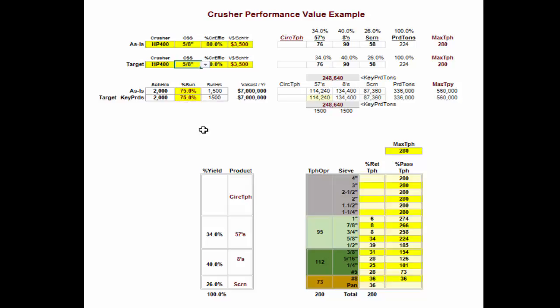So the percentage yield is not always, in fact it's not usually, a good indicator of what the proper configuration of a crushing system is. It's often misleading, particularly when people are committed to using things like flow modeling as a primary methodology for establishing what targets should be. They begin focusing on percentages. You can get your percentages pretty high, but overall tons are what you make your money on, so it doesn't really work so good, does it?